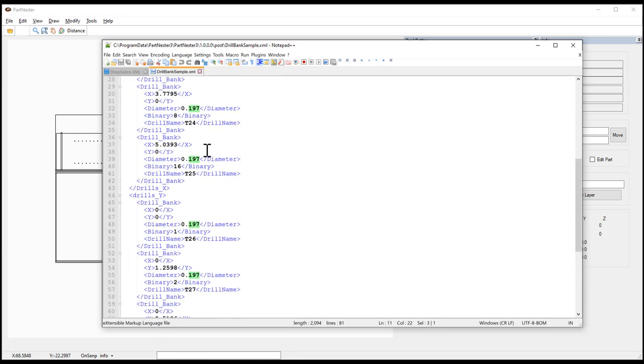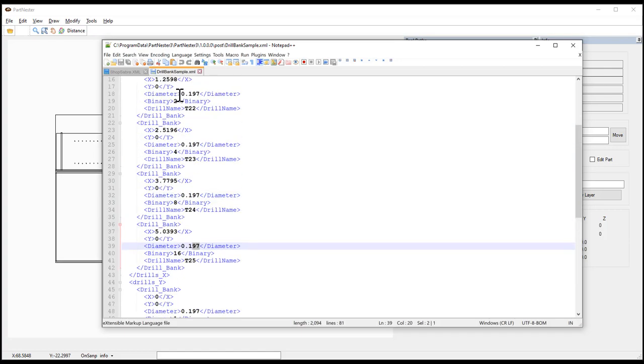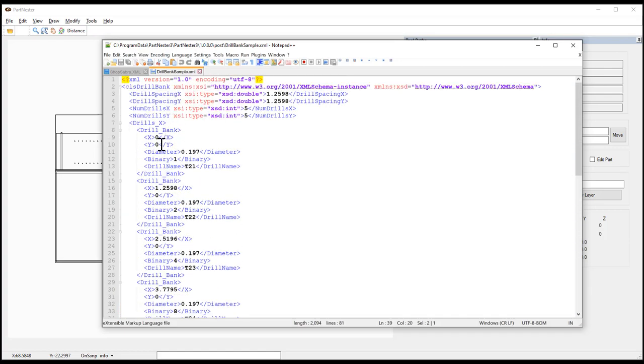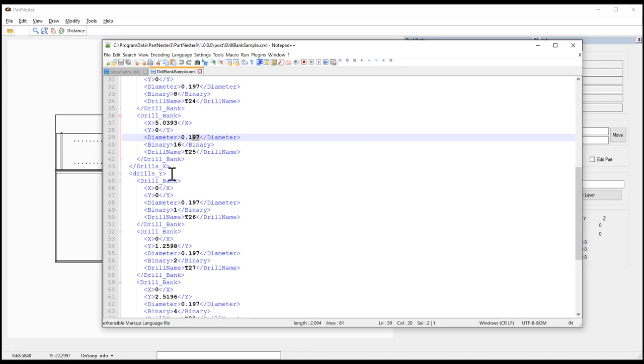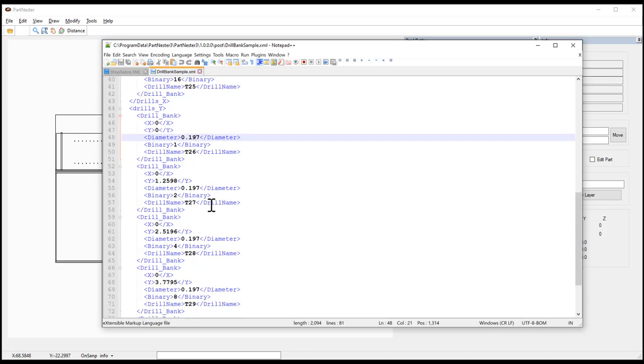If you want to change, if we have an 8mm or a 3/8 diameter in drill position, in this case Y0 is the same as X0, so both of those bits need to be the same diameter in this particular instance. But if we wanted to change the drill diameters, you would just enter in the values that you want them to be.